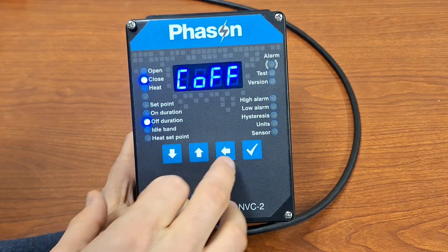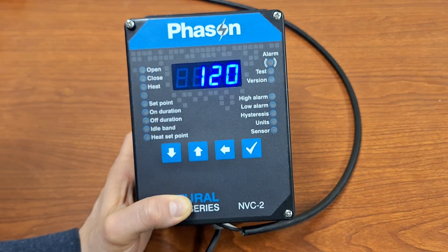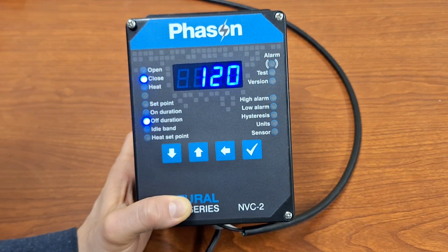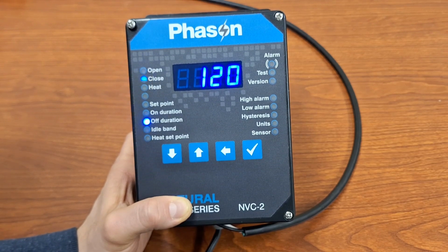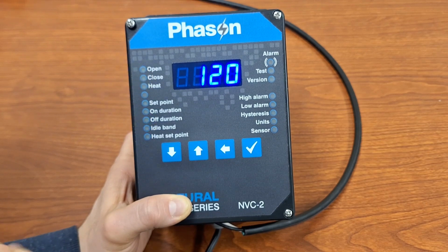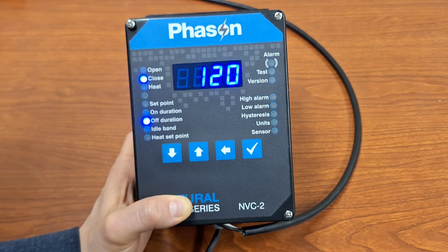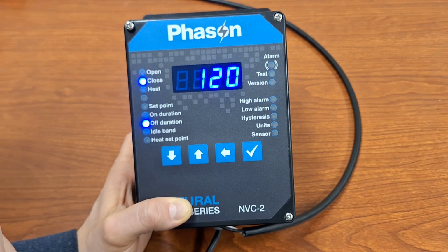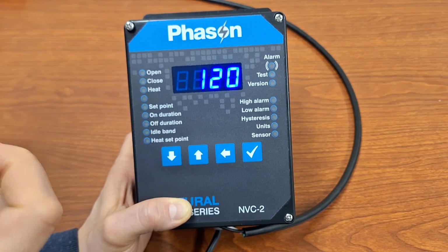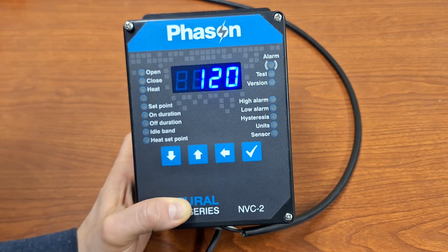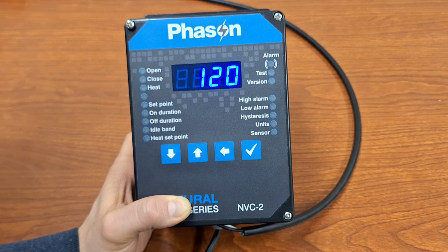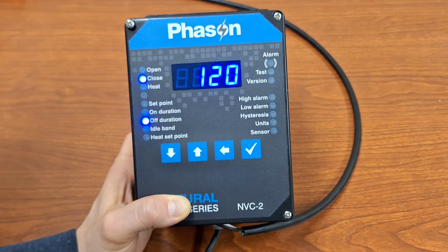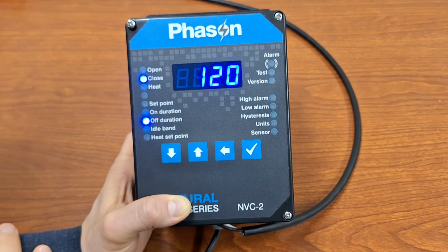and then off duration, 120. So I'm going to close for a full 45 seconds, and then I'm only going to wait 2 minutes, and then I will see, where are we at? So it'll be a little bit of a more aggressive closing, and then a shorter idle time before I'm checking that temperature again, just to make sure that if the temperature is dropping really quickly, that we get to it and we keep closing those curtains and make sure that our inside temp will rise back up into that idle band where we want it to be.